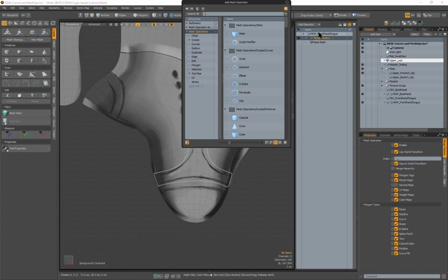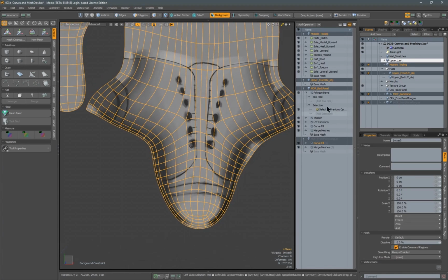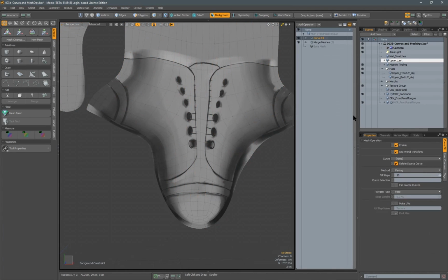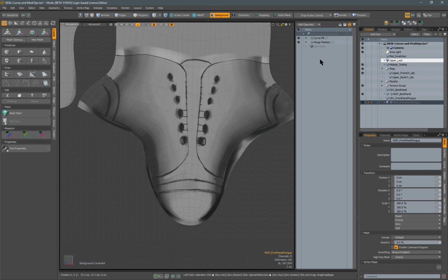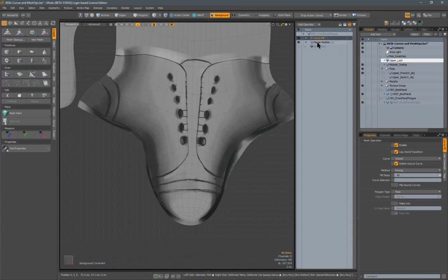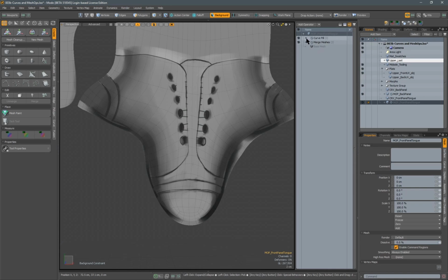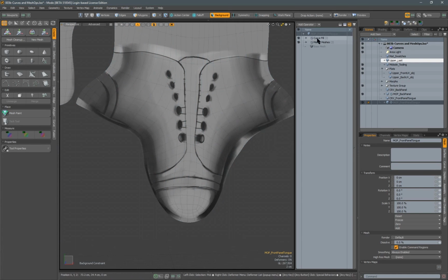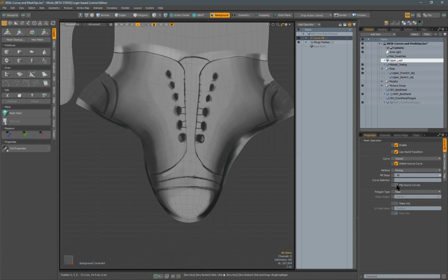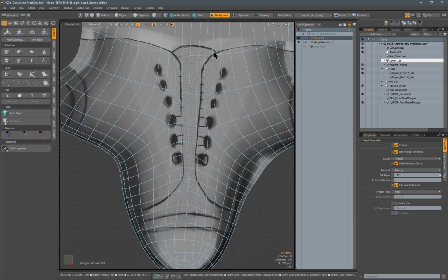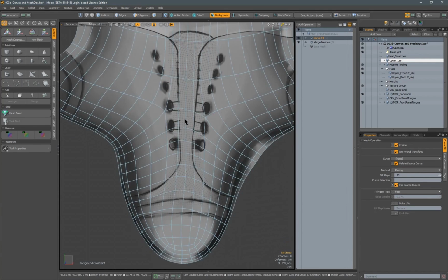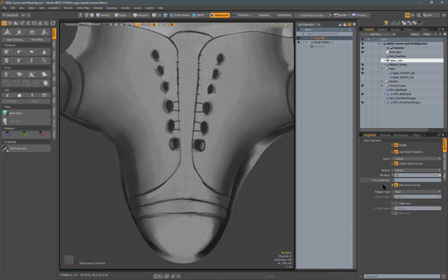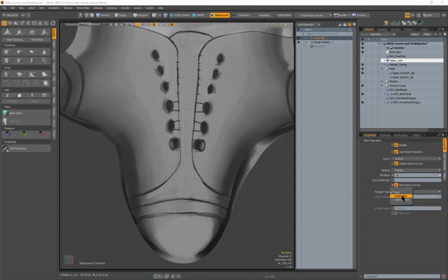And let's add the next one, which is curve fill. Okay. It looks like I hit way too many hotkeys there. All right, so go back to the mesh op here. And it looks like the way that I drew the curve was the opposite direction that Modo wanted. But what we can actually come in here and do is come to the curve fill and then hit flip source curve. And now you can see we have a mesh item in there being filled with polygons. So let's change the fill steps to 5 temporarily. Change the poly type to subdivision.